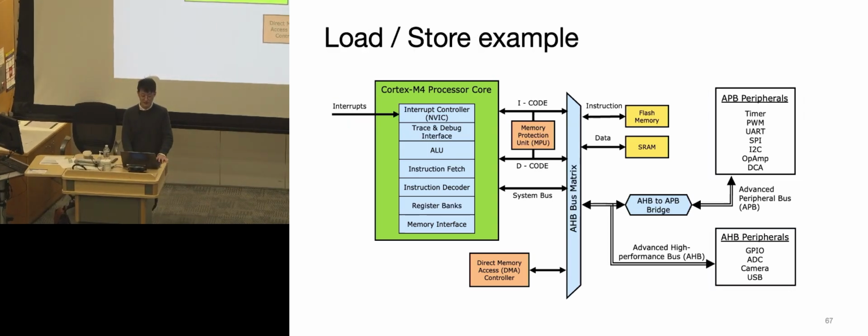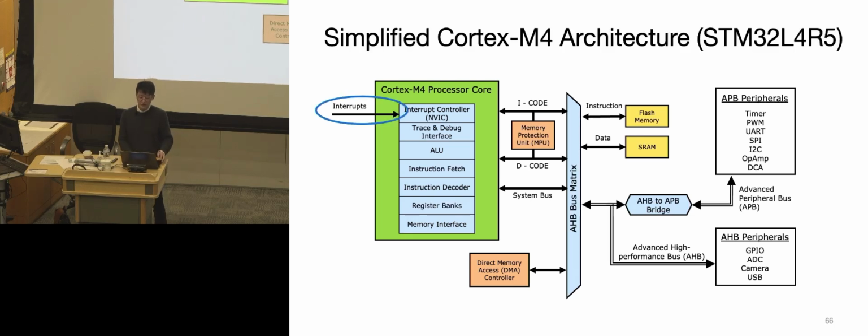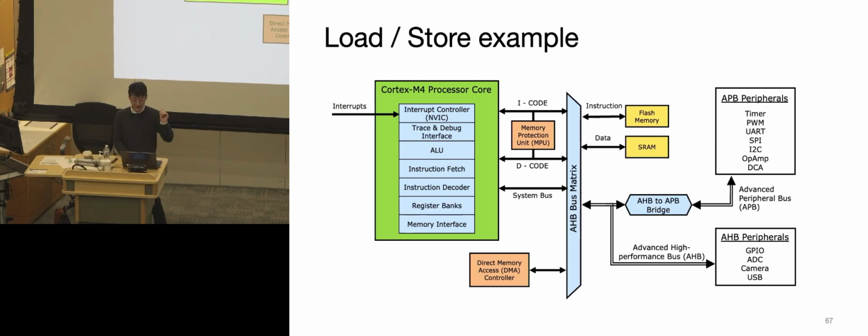And we have interrupts. Basically, it's the way of stopping the normal process of instructions to do other tasks. Generally, this is what happens when you have an input, for example, when a user presses a button and something happens to the system. This is what is going to be triggering it.